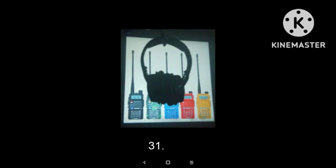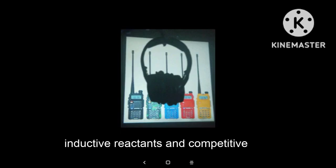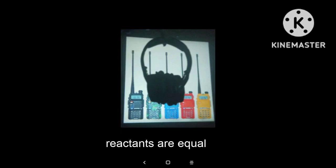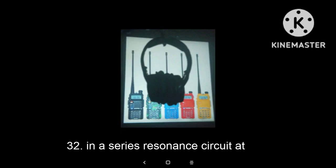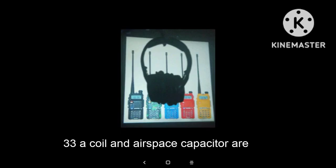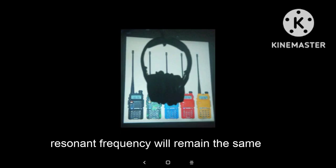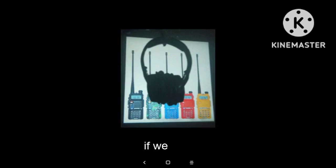31. Resonance is the condition that exists when inductive reactance and capacitive reactance are equal. 32. In a series resonance circuit at resonance, the circuit has low impedance. 33. A coil and air-space capacitor are arranged to form a resonance circuit. The resonant frequency will remain the same if we add a resistor to the circuit.